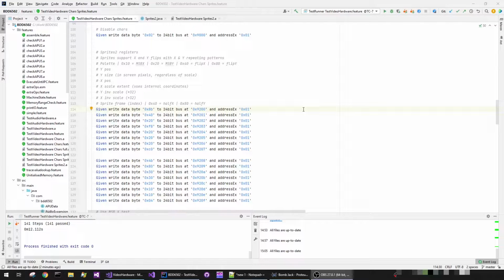In this case, I multiplied by 32, which is shifting the byte left 5 binary places. This gives us enough good accuracy where we can have scale up and scale down for sprites and not have too much complex logic. So I began by actually starting in the emulation code this time.